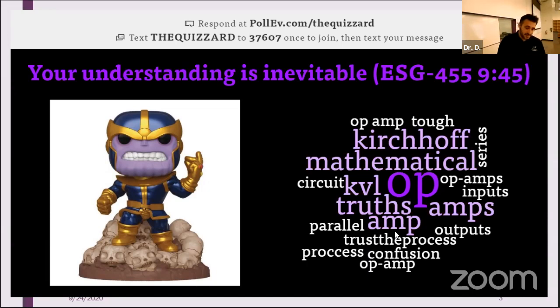Because the way that we're doing this analysis is we're getting everything in terms of either the voltage drop across the capacitor or the current through the inductor. That's what we are getting our model for. Remember, we're only using E sub C and I sub L as dynamic variables, and obviously our input voltage or our input current. Those are the only things.